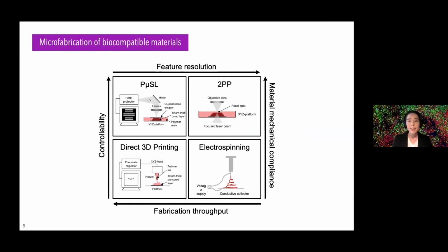While the basic architecture of these structures was simple enough, the combination of the design parameters posed a great challenge for fabrication and could not be achieved by conventional stamping, molding, or patterning methods. So we considered several additive manufacturing and microfabrication technologies, and chose projection microstereolithography. This technique, refined by the Fang group in mechanical engineering here at MIT, features additive maskless photopolymerization of microstructures with good compromise between throughput, resolution, spatial control, and flexibility of fabrication materials.